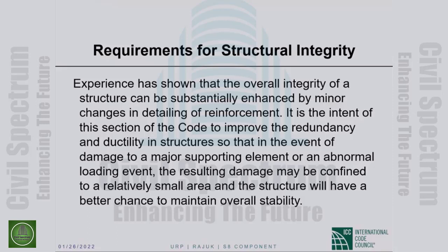When you analyze, read that again. When we design a cracked section for a slab beam, we need to assign torsional modification factors. Should it be between 0 and 1? The question is really framed in a strange way. I don't understand this modification factor. All I know is EI and GJ, the flexural stiffness and the shear stiffness, which is also for torsion.